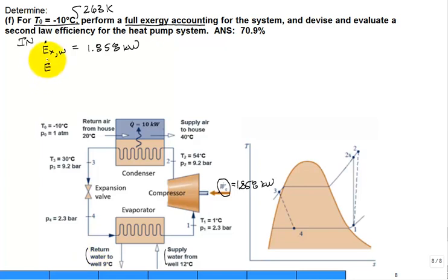So what do we have? We have the rate of exergy transfer coming out of the water. Let me do this, water. The well water. All right, how would we calculate that? Well, we have the mass flow rate of the water. We just calculated that. And if we could get the change in the flow exergy, it comes in high and leaves at low.